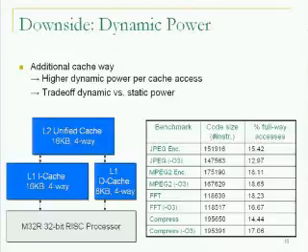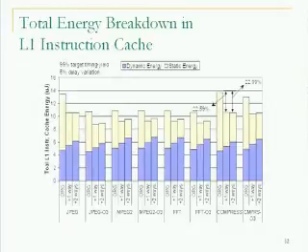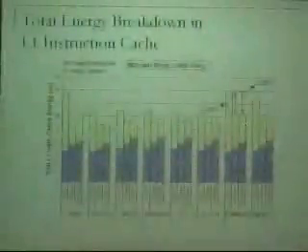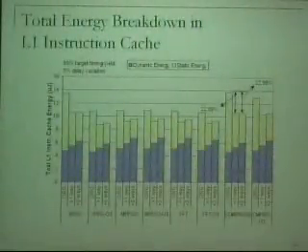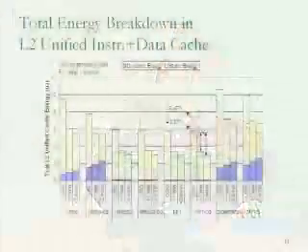And the results finally on instruction cache would be like this. On the compress benchmark, with one additional cache way, you can get around 22%, but the second extra cache way does not help you as much as before. So leakage saving is almost the same as this case. So the 25% additional area would not be worth it.